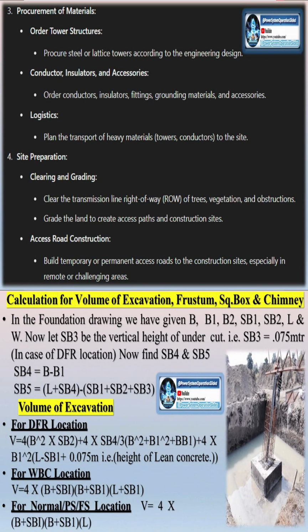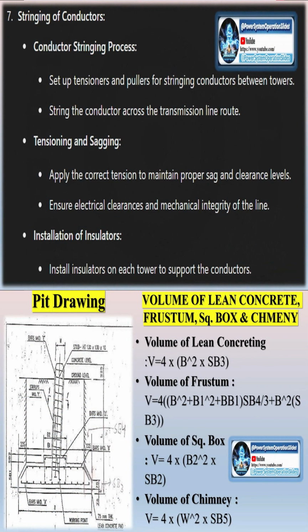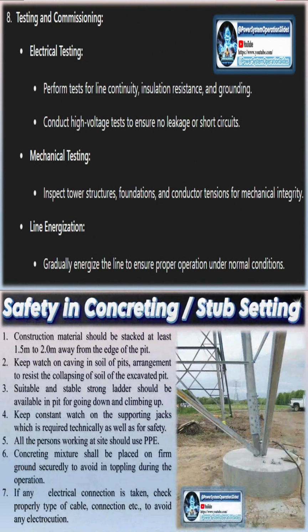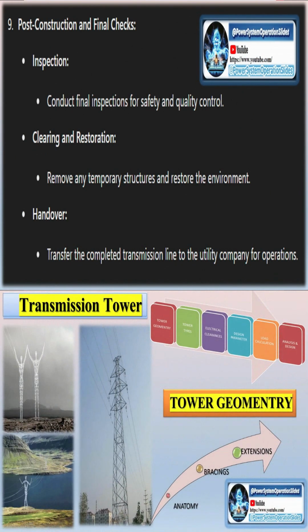The first step is to conduct a preliminary feasibility study, which involves analyzing multiple potential corridors for the transmission line. This initial study considers several factors, including the geographical layout, existing infrastructure, environmental constraints, and technical requirements. One of the key aspects of this phase is the minimization of environmental and social impact.